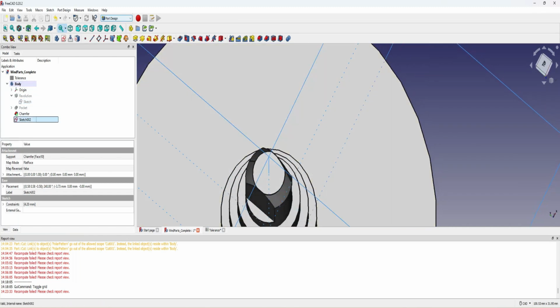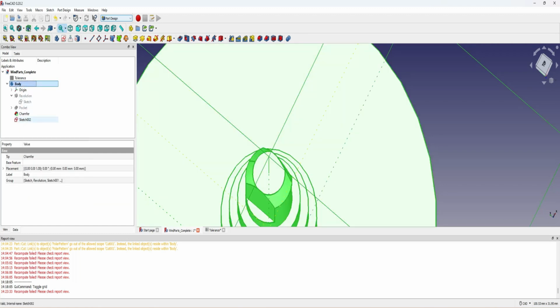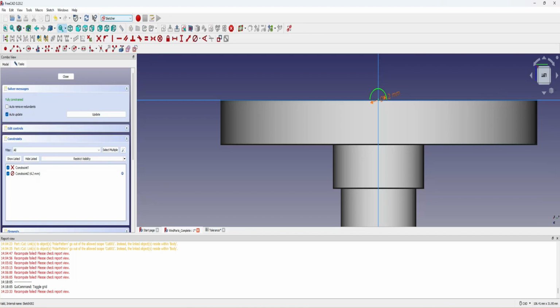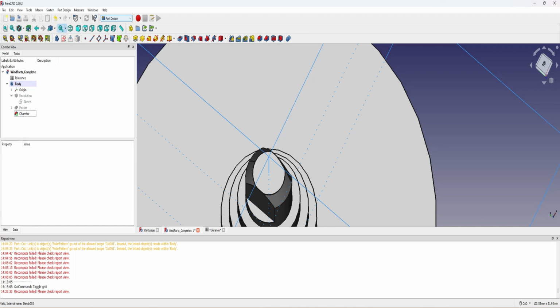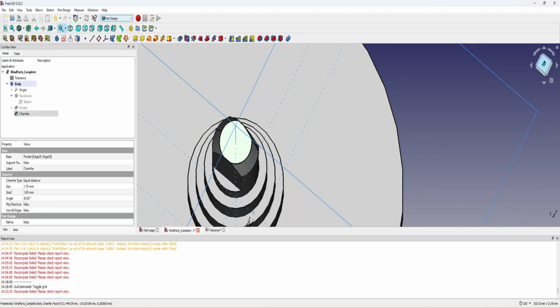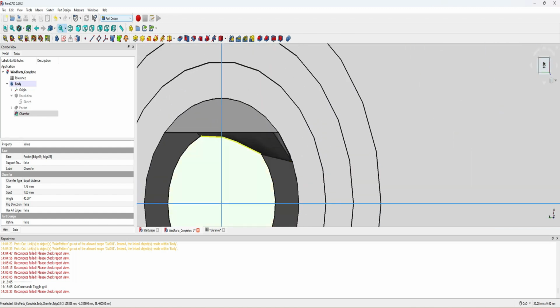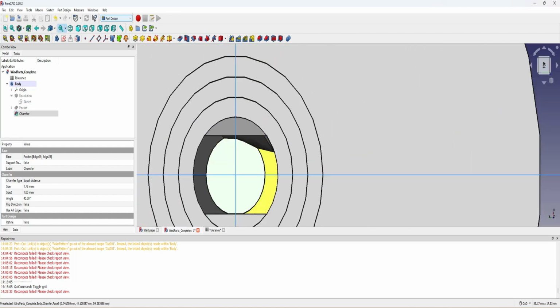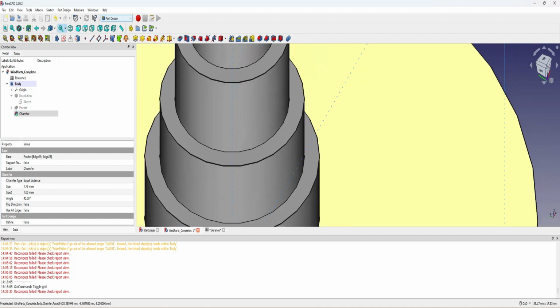So in my case, that portion updated, but it had also broken the chamfer that I had made previously. So first I thought it actually messed up the cut portion itself, but it was really the chamfer that got broken because the original circle had gotten moved off the top and somehow got moved down below. So I just had to go back and essentially delete some of the steps that I had done previously and then recreate the circle on the top in order to do the hole.